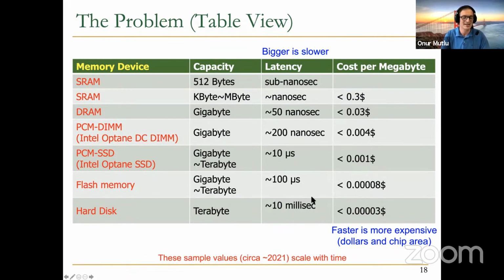It's very interesting to think that, because latency is a lot harder to reduce than cost. Cost is really packing bits in a given millimeter square, right? And that's easier to do as long as you can reduce the size of the memory cells, which is essentially technology scaling or Moore's law. You can basically put more devices in a given area due to technology scaling.